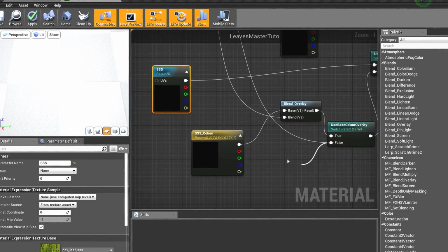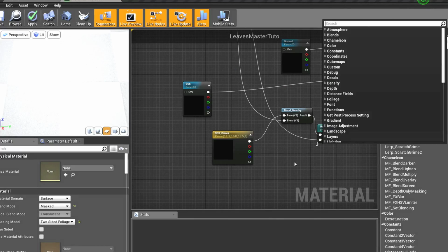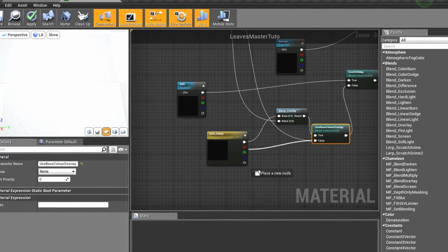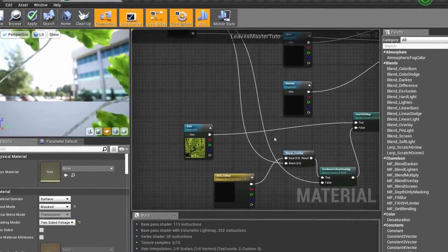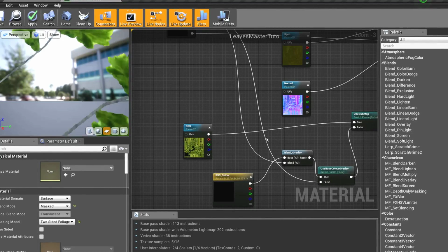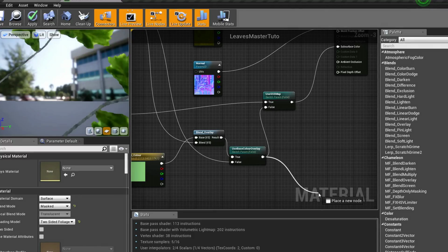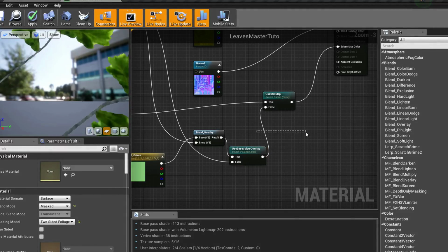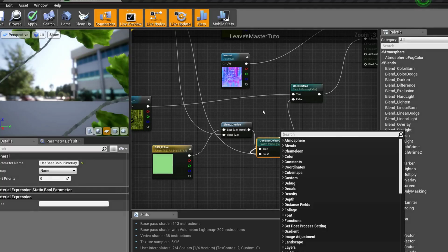So what you can do is drag out from this input. Now remember, a node can take only one input. So if I drag this out and add a node, it will be added between this connection only if it is supported, because a node can take only one input, while if I add a node from here, it will generate as a different node away from this link, because nodes can have a lot of outputs, I mean a lot of output connections.